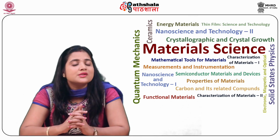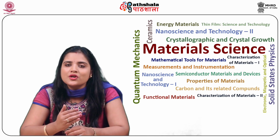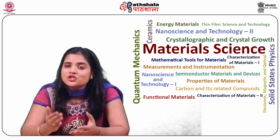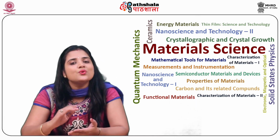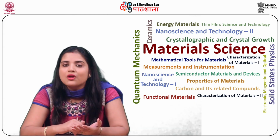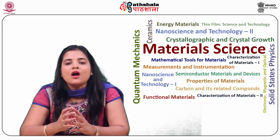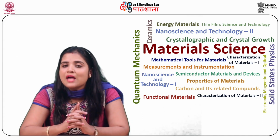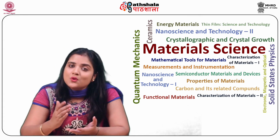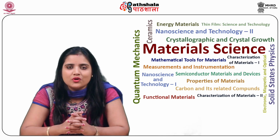The first one is the variable resistor networks. In this method, D to A conversion is accomplished by designing a resistive network that will change each digital level into an equivalent binary weighted voltage or current. To understand the meaning of equivalent binary weight, consider a 3-bit binary signal which has 8 possible digital signals. Our aim is to convert the 8 possible digital signals into equivalent analog voltages.